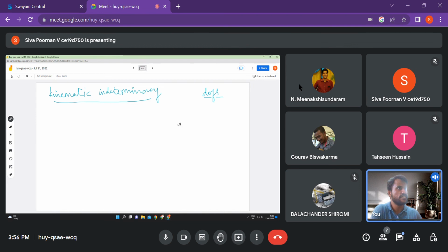So you have, let's say, a truss system. Let's say we take a single bar and we want to know how this bar is located after deformation. It would have moved somewhere else, right? Let's say that after deformation it's looking like this. It would have elongated and so on. This is a part of a truss, a single bar, and after deformation it would have moved somewhere like this. So if we need to entirely describe this deformation, how many nodal coordinates do we need? We need to know the displacement of these 2 points. In other words, we need to know both the x displacement and y displacement of this point from here. So 2, and again we need to know what these two are. 2, right?